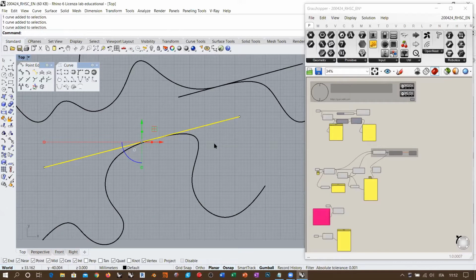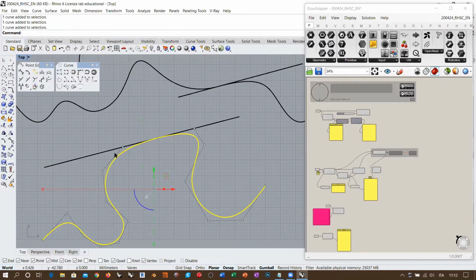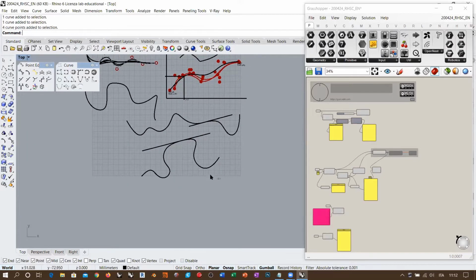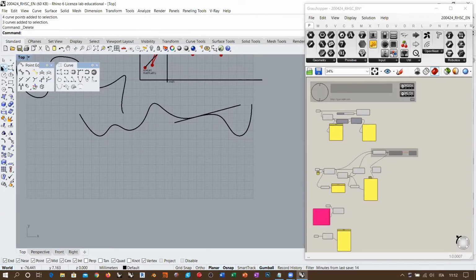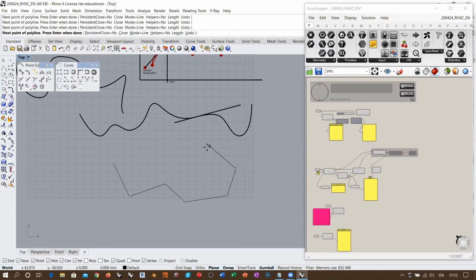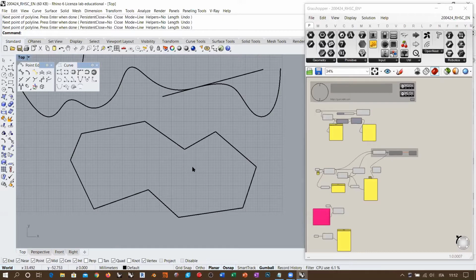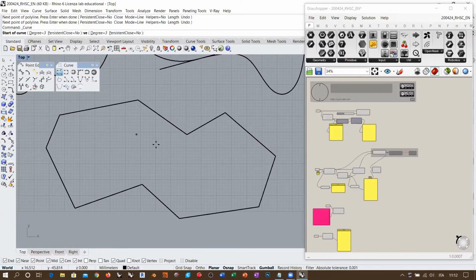Okay, so we can define, for example, the tangency of one NURBS curve to a specific line. And we are seeing that this happens by aligning three control points. So this is already something that has some use for us. For example, if I have a region in our plane, but it can also be a 3D region, and we want to draw an organic shape inside this region without exiting this region, then we must take into account this second rule that we just saw. By aligning three control points, we become tangent to a specific line.